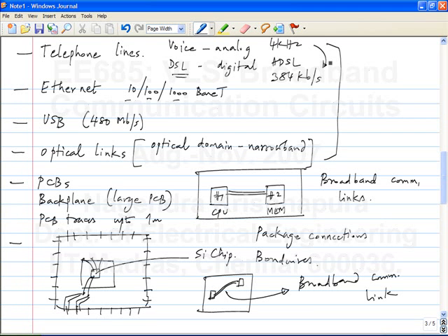Voice goes through the cable without any problem. Voice is not a digital signal, but I'm just concentrating on the frequency content of the signal. But if you transmit this 1-0 kind of binary digital data through a telephone line, on the other side you will absolutely not be able to recognize the 1-0 data. So this whole DSL modem is about transmitting it in a correct way so that you can recover it properly.